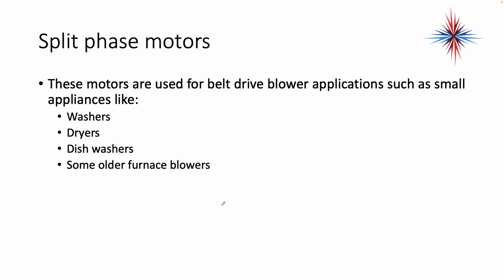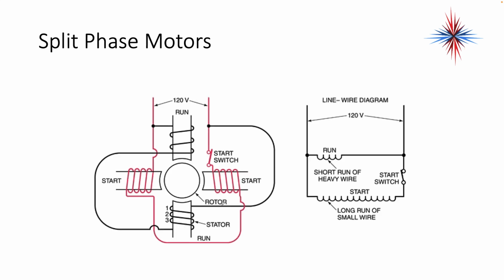Split phase motors are used for belt drive blower applications and small appliances like washers, dryers, dishwashers, and some old furnace blowers you'll still see. I mean, very old furnace blowers. You'll still see split phase motors.